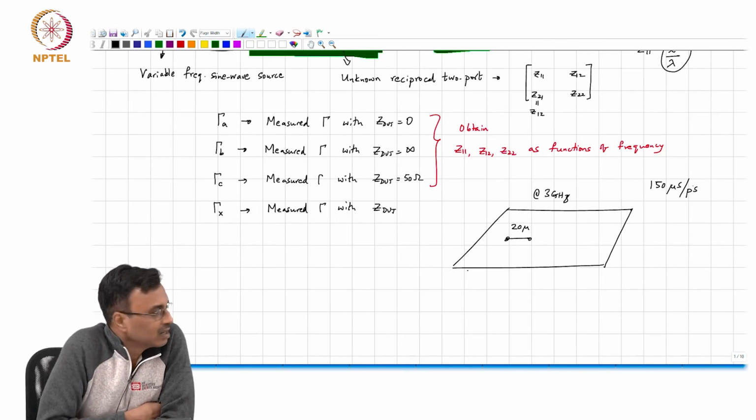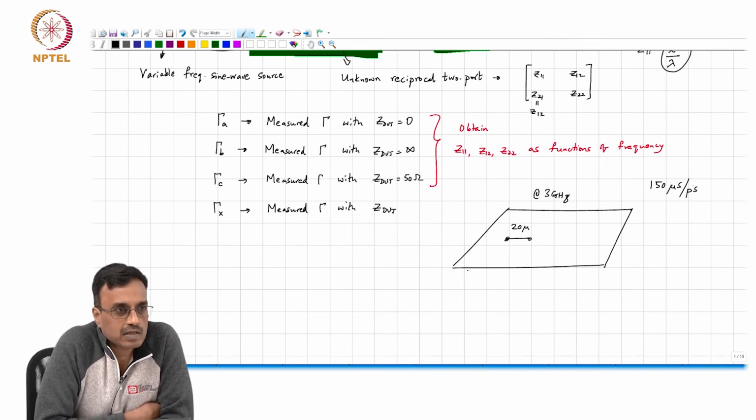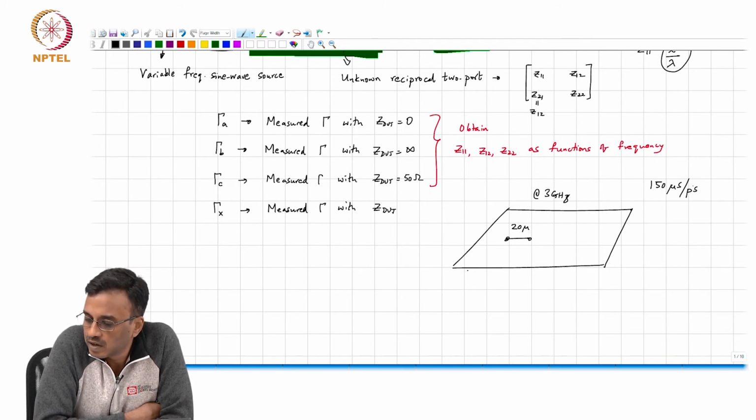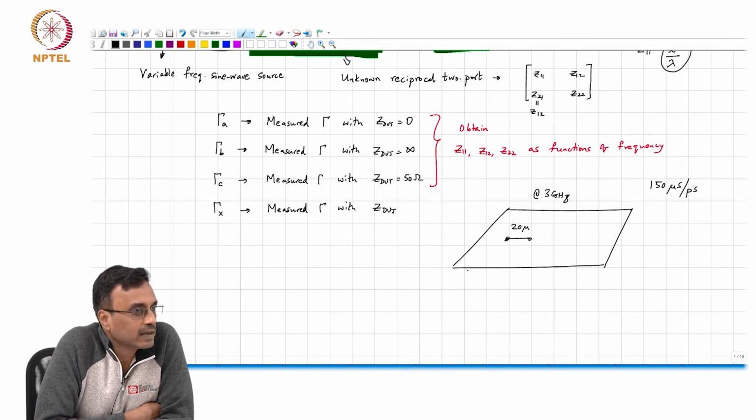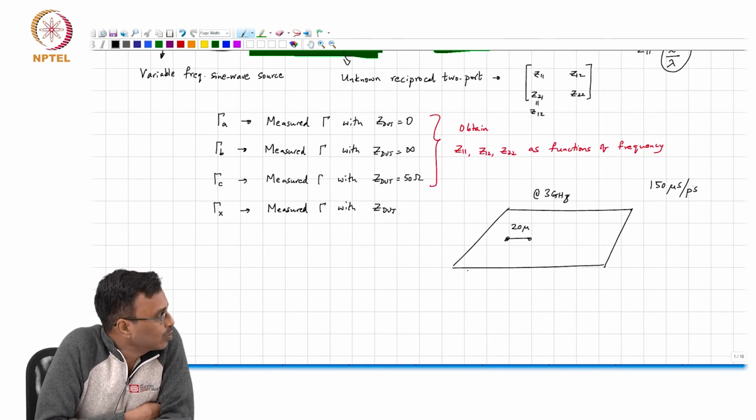If you have a millimeter on silicon, it's about 6 picoseconds, right? 6 to 7 picoseconds. Anyway, so 20 microns is how many picoseconds? How long will light take to traverse 20 microns? Yes, Karthi, what do you think? Okay, right, something like less than a tenth of, about a tenth of a picosecond, right?